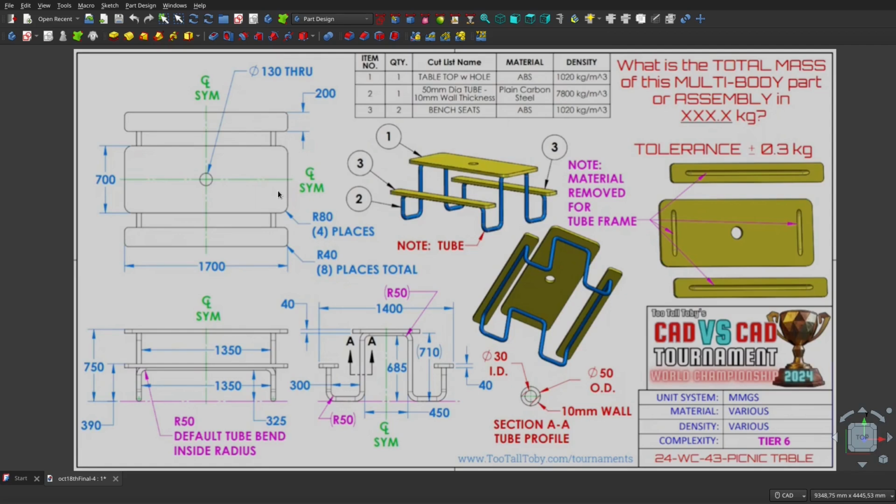The image you're currently seeing, showing the views of the table, will be imported 3 times and arranged accordingly, as previously explained. According to the workflow we're using, all the data defining the structure and shape of this table will be stored in master sketches, and possibly in some secondary sketches. From there, the rest of the project can be completed using the Part Design workbench, employing tools such as Subshape Binder, Additive Sweep, Subtractive Sweep, and Multi-Transform. Alright, let's get started with the actual modeling.